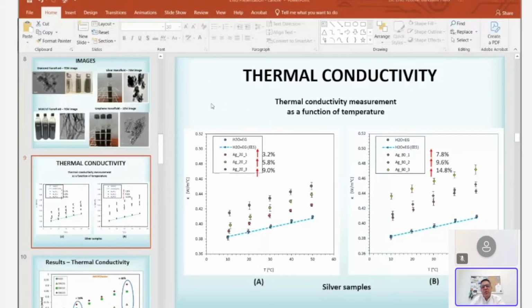Here we measure the wall temperature, and we measure the fluid temperature inside as well. We apply a heat flux on the wall, so with this you can calculate the heat transfer coefficient directly. We can test base fluids, water, ethylene glycol, and thermal oil, for example. We test this a lot, and we can compare these results.